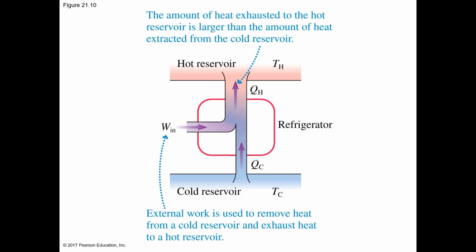I hope you've read about that in the chapter. Here's the heat diagram for the refrigerator. Now remember, this little schematic doesn't show you anything about the technical details of the heat engine. It doesn't even have a picture of the working substance, whether it's a gas or steam. The only information it contains is the relative quantities, or how much work you have to put in compared to the heat. The thickness of the bars has some significance, but there are no numbers. And it shows you the direction in which energy flows.